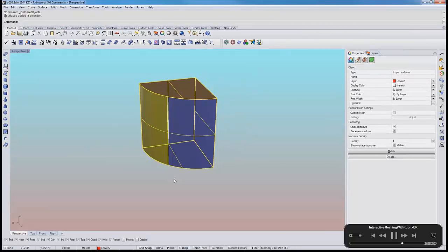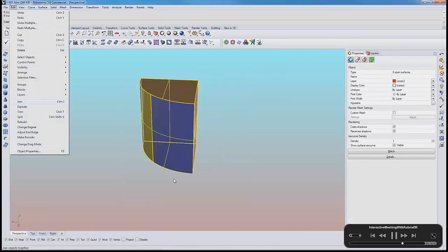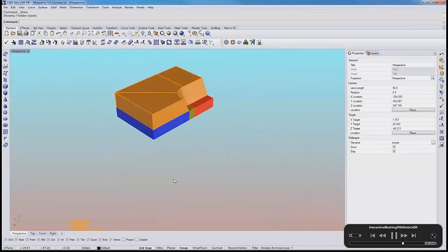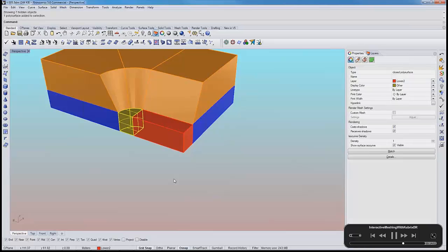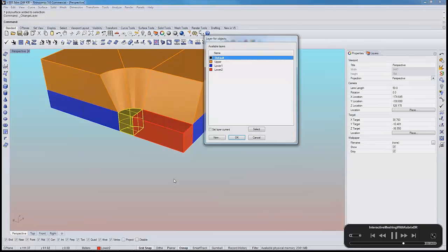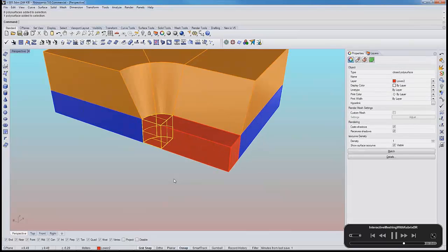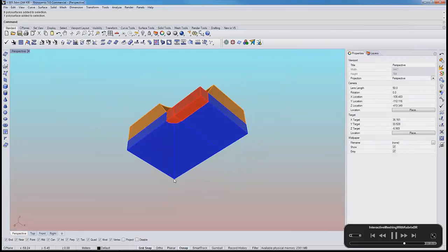box topologically. Now this lateral surface is made out of 2 surfaces, which should match the 2 surfaces of the other solids. So in the overall number of solids in the model, we haven't made any changes, but the lateral face of that quarter cylinder has been split in 2. And again, every solid goes into its right layers in preparation for meshing for FLAC3D, so that the resulting mesh blocks belong to the right groups in FLAC3D.